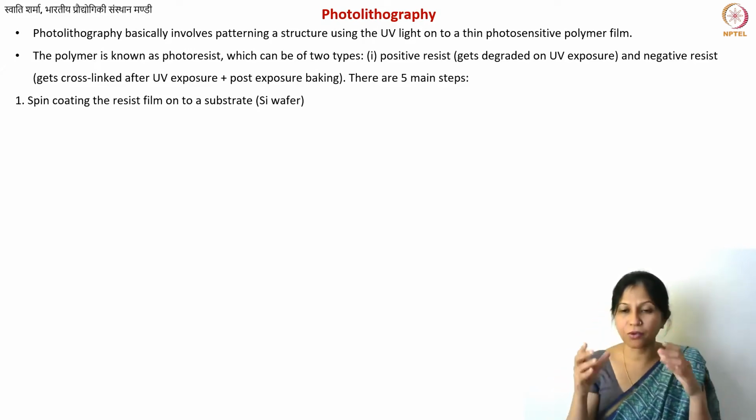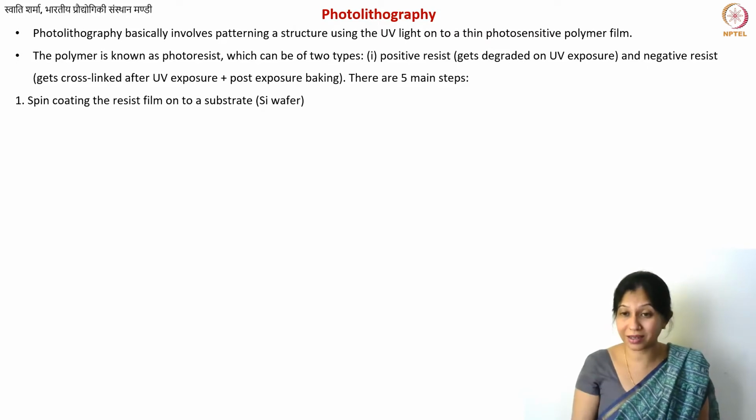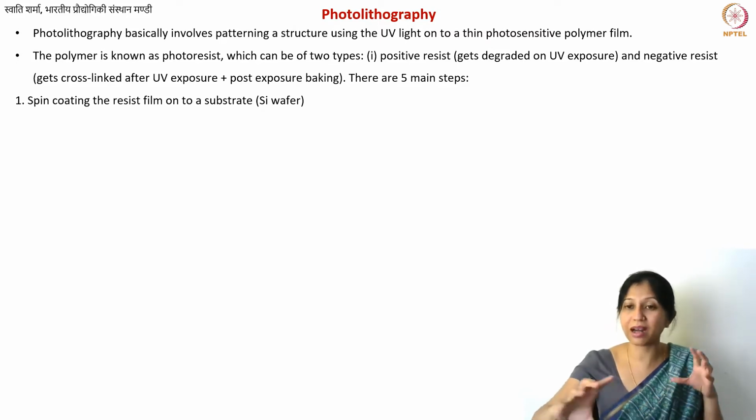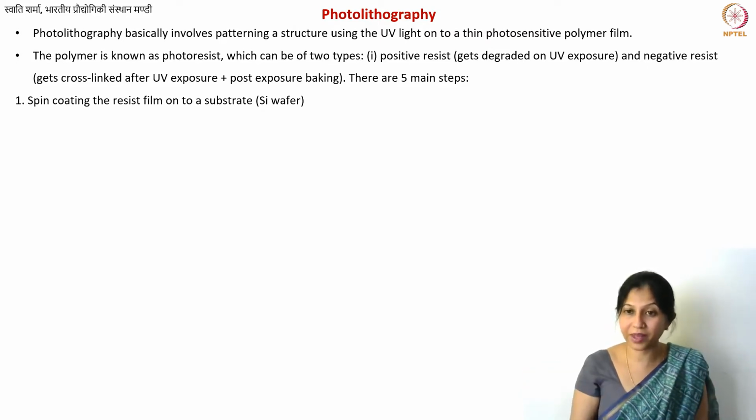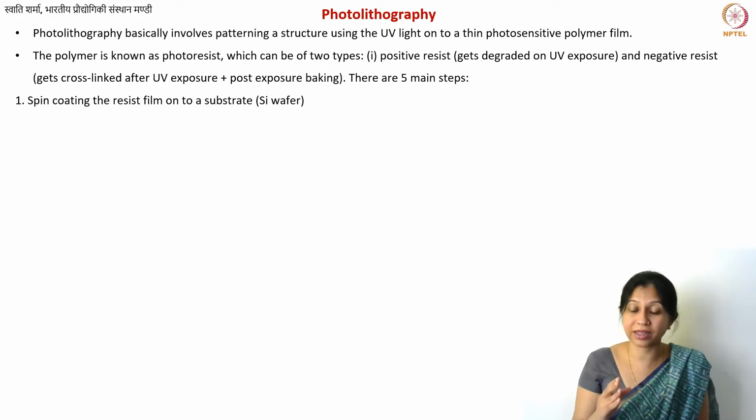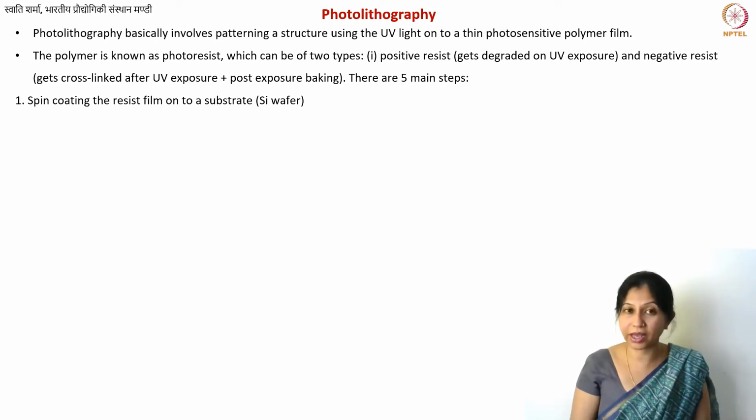They are typically either 4-inch or 6-inch in diameter, and these are actually single crystals. You can grow really large crystals of silicon, and then you can make wafers out of it. You can slice them into thinner wafers. Of course, you can also have P doping or N doping in the wafers, and different crystal orientations, 100 or 111 plane. So again, that's a separate topic altogether.